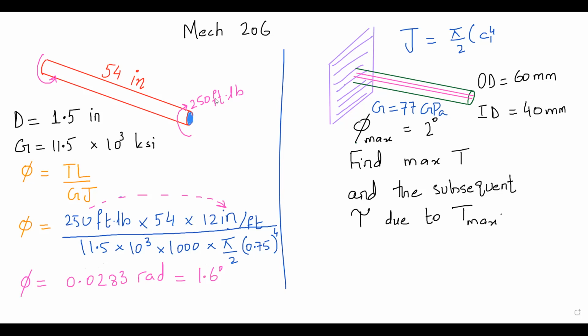So you see, it is a very physical idea, but unfortunately it is in feet-pound. So let's do the problem in SI, because most of us, including me, are comfortable in SI. Now for design purposes, you also want a rather limited twisting, right? So if phi max is given to me as 2 degrees, give me the maximum torque. It is a hollow shaft, please remember.